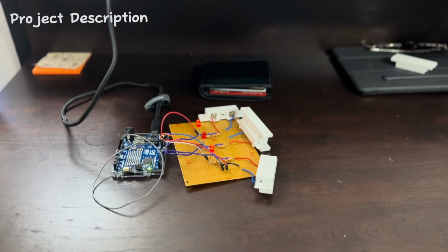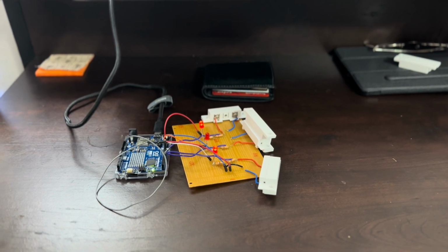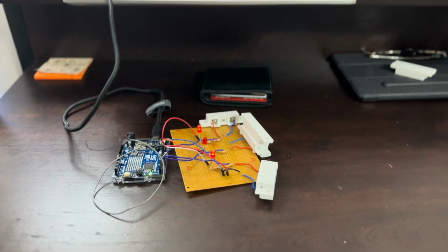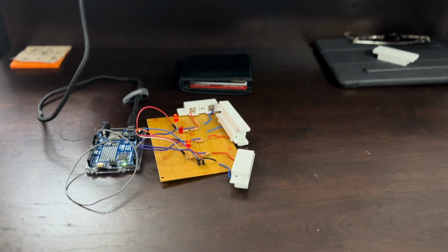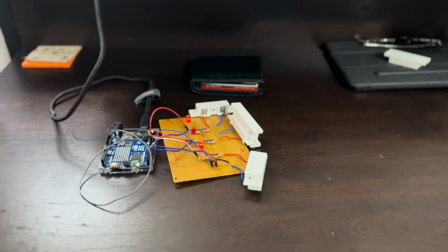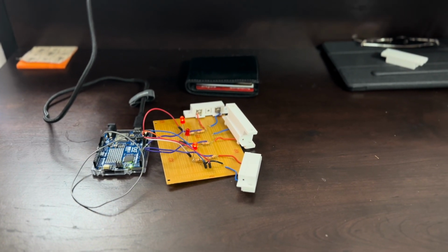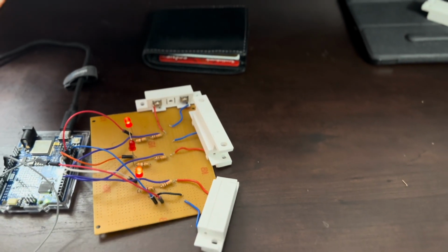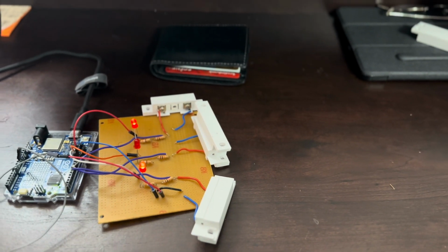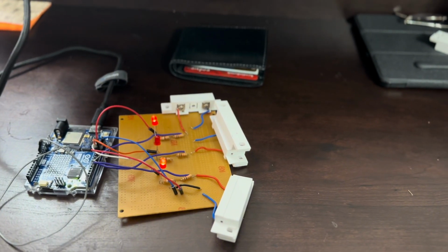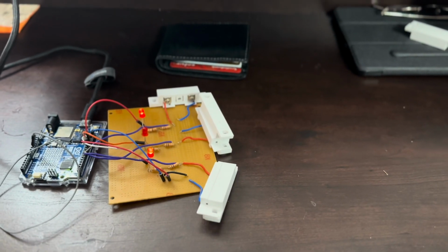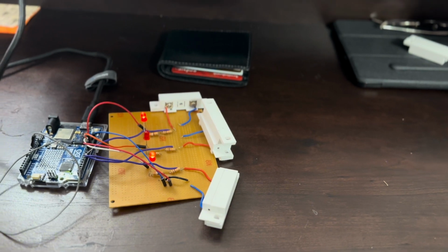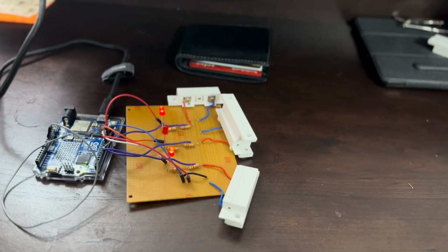This is the detailed description of my hardware components as well as the software components relating to the whole project. So to simulate the doors, I used 3 magnetic reed switches, which are initialized as normally closed. This is because I want a flow of current when the reed switches are not in contact. As you can see over here, the middle reed switch is in contact, therefore it will register as 0. And when the reed switches are open, it will register as a high. I use this approach because I want the system to let me know if the door is open and at what time.